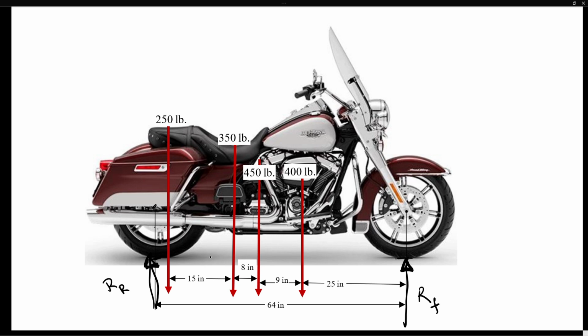Now here is one thing: because it's a roller surface, as we have explained before, there will be only vertical reaction from the ground. For any smooth surface or roller, you only have a vertical reaction. So we draw the free body, and we have all the forces done, including the reaction forces. Now to find out the forces, you just have to take moments in a way so that you can cancel as many of the unknowns as possible. Here in this case you only have two.